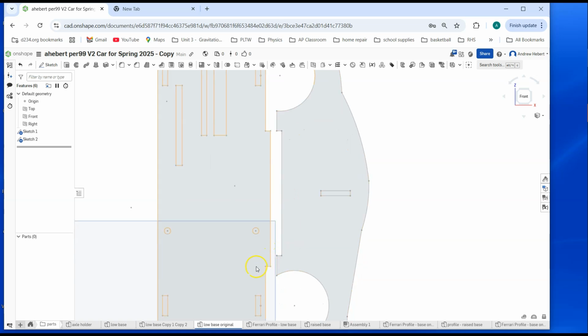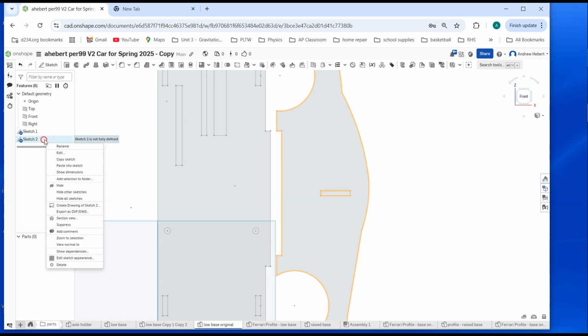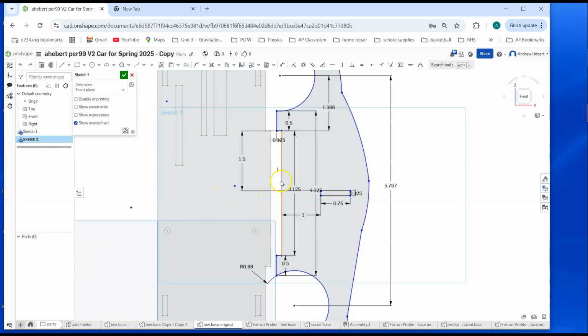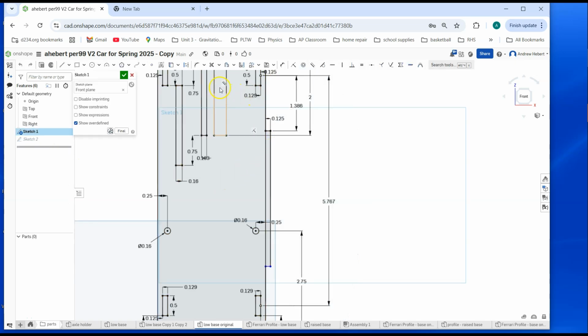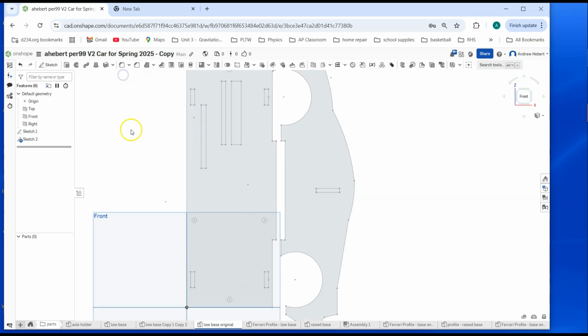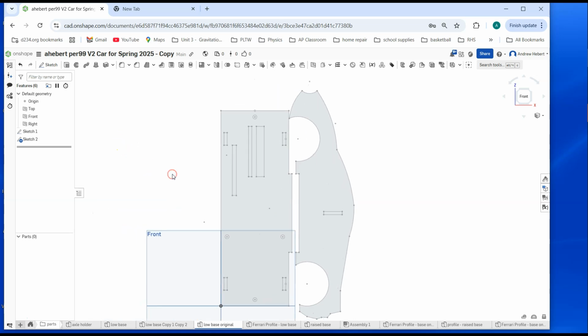Now, the bottom has not been correctly sized, so this needs a reference also, right? Where is this point? Well, I could just say, how long is this slot from here to here? That's probably the easiest way to do it. So let's go into Profile, and it says that this piece is 3.125 inches. Come back to sketch 1, and let's make this piece exactly 3.125 inches long. Hit the check mark, and now it looks like it's going to fit perfectly.